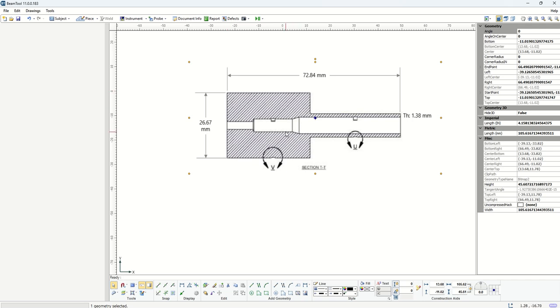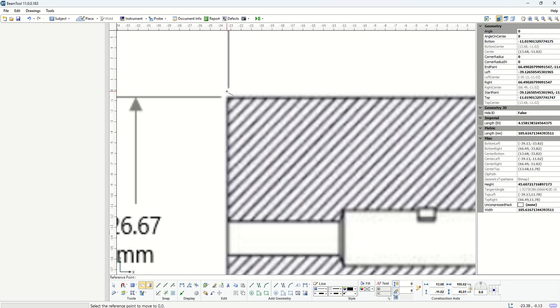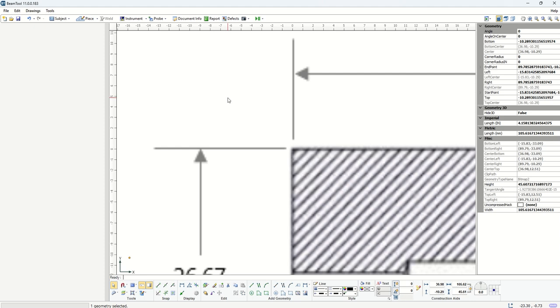But before I do that, the next thing that is useful to do is to set this image from one reference of choice to the origin of our whole workspace. That's another tool here, where I can say move drawing to origin. If I click move drawing to origin, then I can choose which corner or which location of this image I want to go to the origin, which is 0, 0. In this case, I want to choose this corner. So if I click on this corner, you notice that this corner is automatically moved to 0, 0.